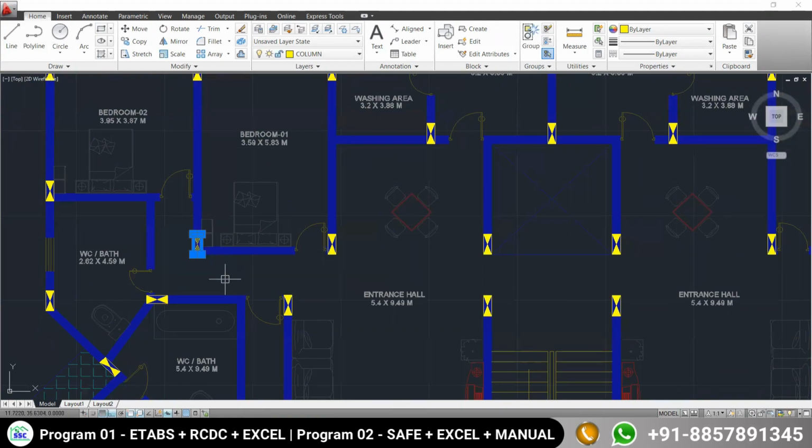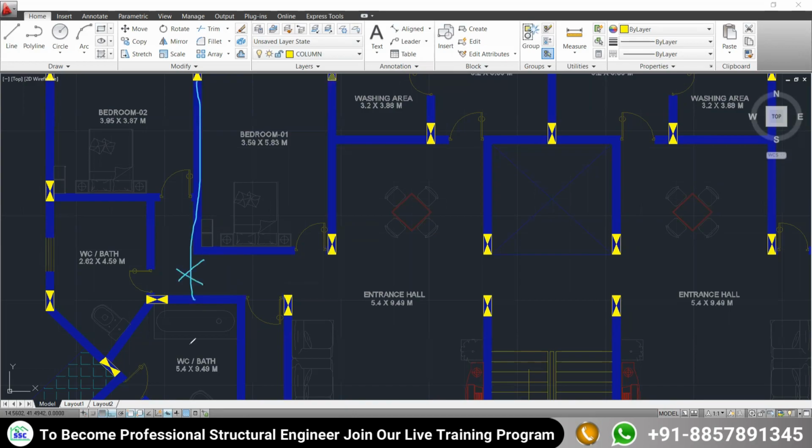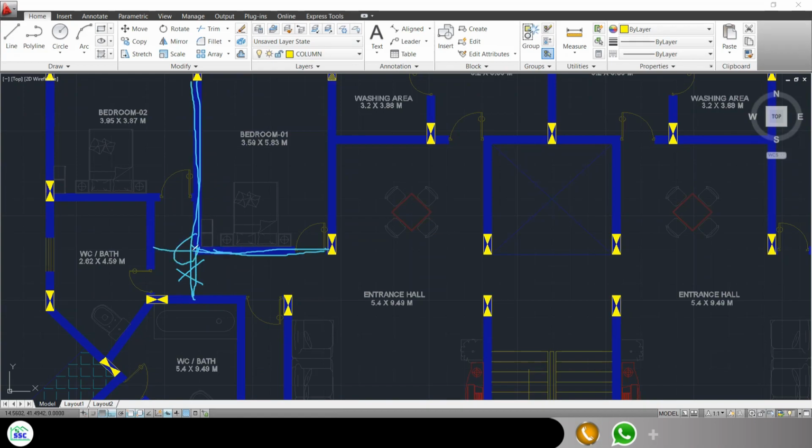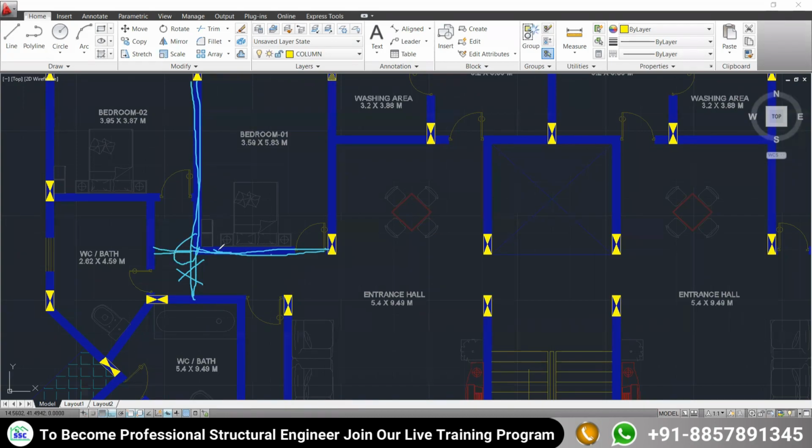If you are not taking the column here, then what will you do? Will you take the beam from this point to this point? No, it is not going to work. Then put it beside the door? The beam is coming from this side, and it is already projected over a very long span. If you take the beam to rest over this one, you can't keep it continuous. It does not make sense to do it like this.